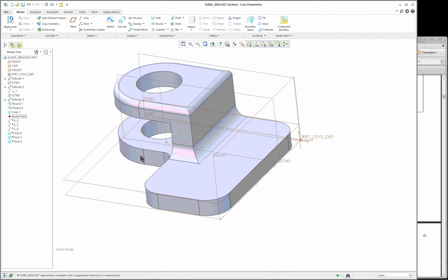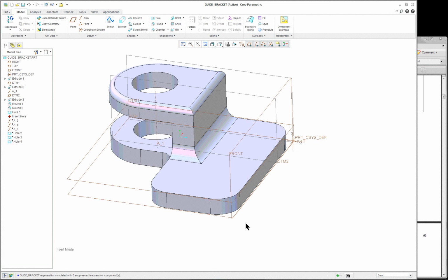So I'll do it one way and then I'll show it to you the other way. Basically what we want is an axis down the middle. Whenever you make a circle, Creo will actually create an axis. But when you make a round or an arc solid or surface, it will not give you the axis down the middle. You have to put it there if you want it.